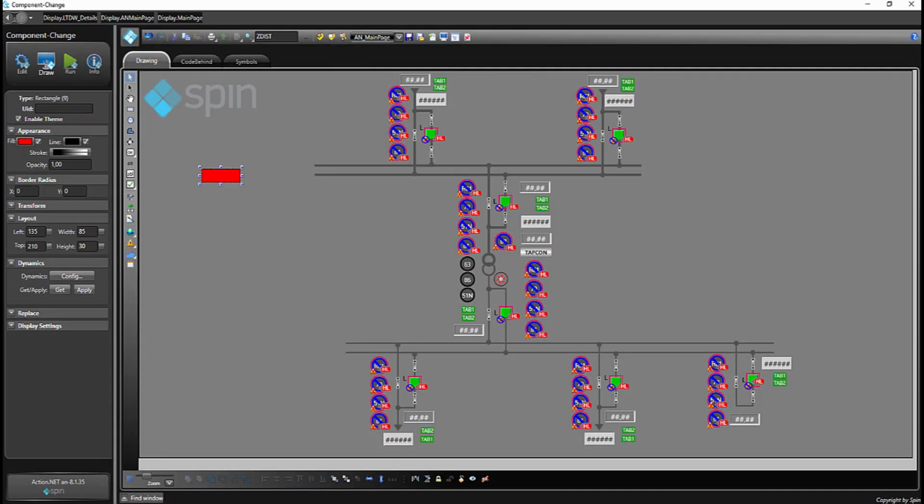Just like we did with bay color 2, we can do it with bay color 1, and, if we want to change the bay color 1 and 2, just change the comment attribute to a new color. So, this is how we adjust the colors of the single line diagram to utilities culture.